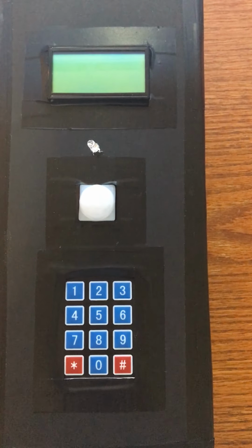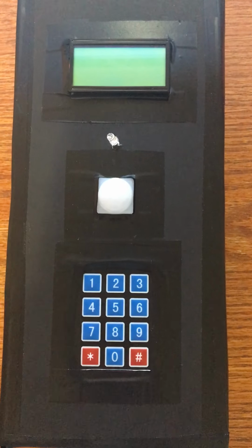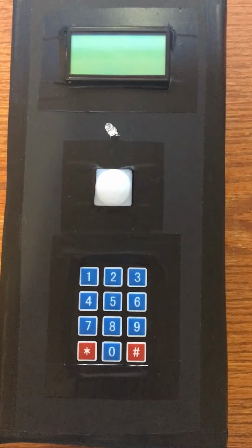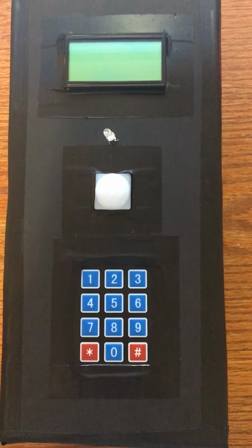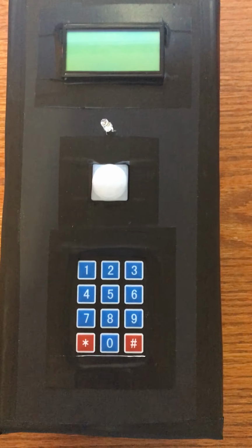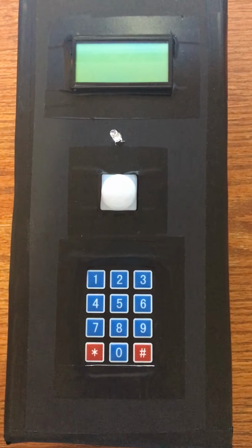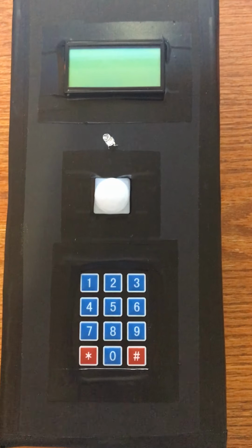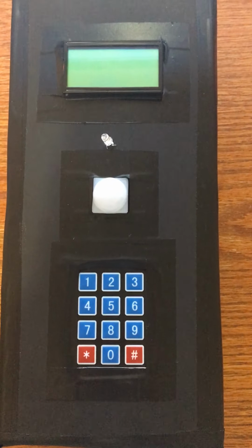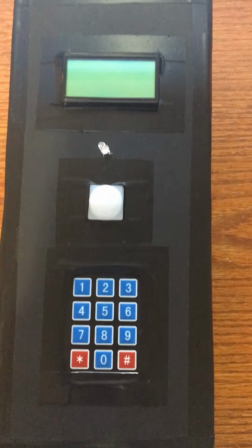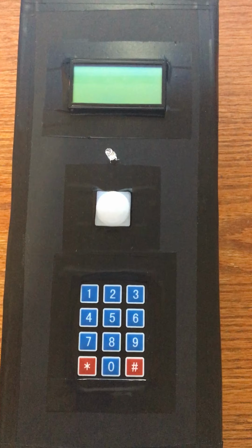During the alarm deactivated stage, the SPI is initialized and the DAC is configured to output a DC voltage of 1 volt, turning off the LED. Next, the software architecture initializes the LCD, clears the display, and sets the cursor at the beginning of the first line. The software architecture then displays the message, alarm deactivated. Then the software architecture reads the keypad input value. If the star key is pressed, the alarm system resets and returns to the countdown stage.